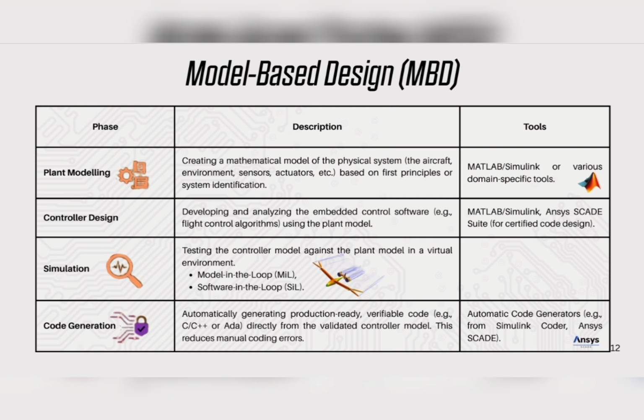Plant modeling. Develop a mathematical representation of the aircraft, sensors, actuators, and environment. This can be based on first principles or system identification. Controller design. Develop control and signal processing algorithms against the plant model, refining gains, filters, and logic.